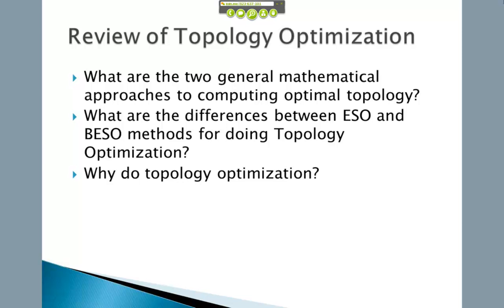You have to look at that and decide whether to do it with a casting process, to do it with a milling process. You have to decide how complex. And we've got some examples that you'll see in this lecture where they looked at it and said, that's way too complex, we're going to simplify it. And by simplifying it, they still left in more weight than the optimal that they needed, but it was easier to manufacture by doing that. So there are trade-offs.